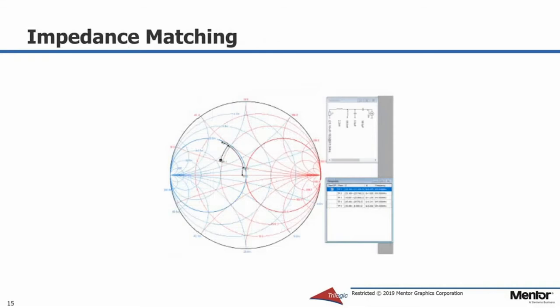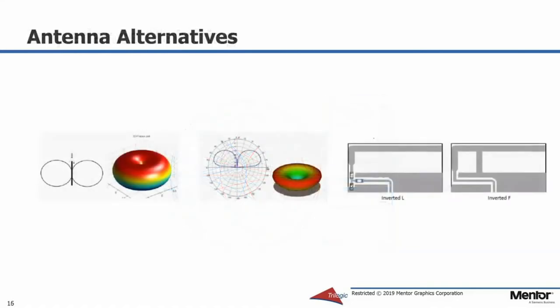Impedance matching in required areas of the design must be adhered to for optimal results, especially between the radio IC and antenna. More than one antenna option will normally be provided. The bigger, the better when it comes to antennas. But if space is an issue, a PCB trace antenna or chip antenna are alternatives.